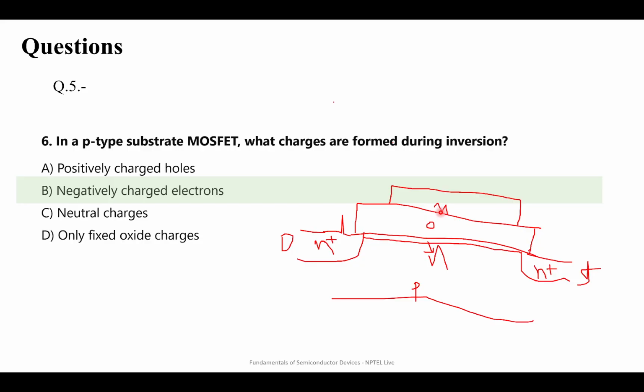The modulation of current is through a field effect, so that is why it's called a field effect transistor. You give a field across your oxide by applying a voltage on the metal part, and the substrate is also something you apply a voltage to. That's called the body.